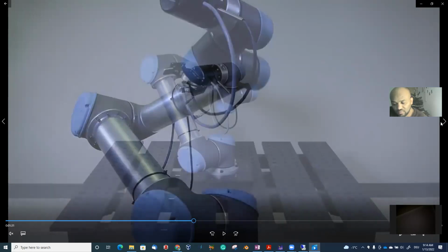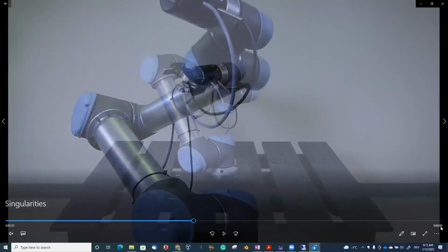Sorry, it's true, but I think Alireza's explanation is not complete. It's true that moving the robot arm depends on the programmer's decisions, but those decisions are inspired by the space where our robot is placed. For example, imagine a robot will pick a car dashboard and put it in the car. The dashboard is so big that we don't have much room to move the arm, and it may cause accidents and damage the product the robot picks.